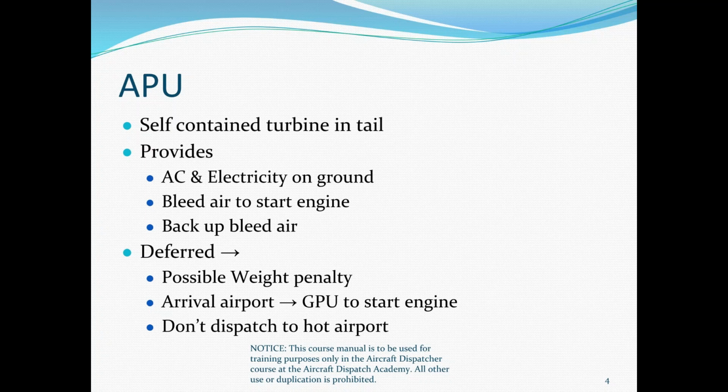What about passenger comfort? What is it doing on the ground? It's creating a vomit comet. So on the ground, it's going to be extremely hot because they don't have the engine running yet. So the APU is providing that bleed air while it's sitting on the ground, and the bleed air controls our environmental system, right?